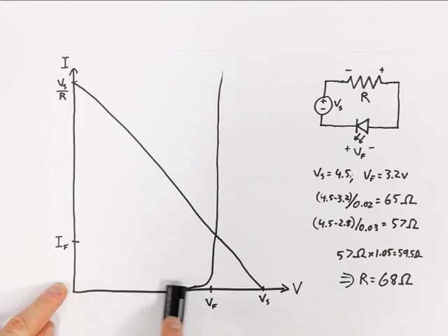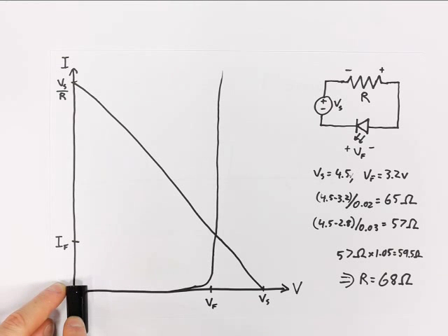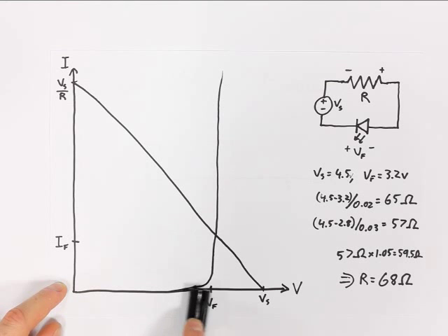And that's assuming, of course, that voltage is held constant. But we see that that's really resulting in our voltage falling off the elbow of this curve into a region where it's very difficult to control. And if we tried to set up our current driver circuit to do that, I suspect the LED would either flicker or possibly not light at all.